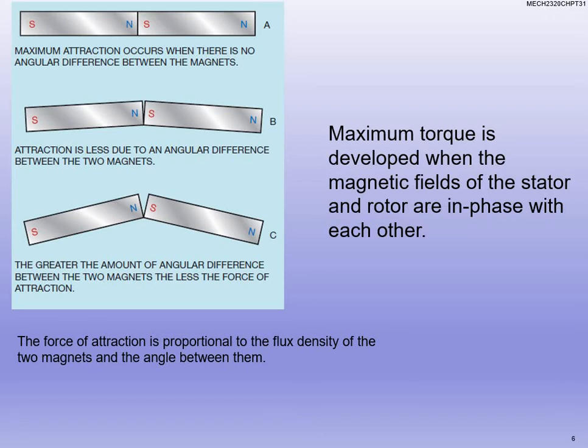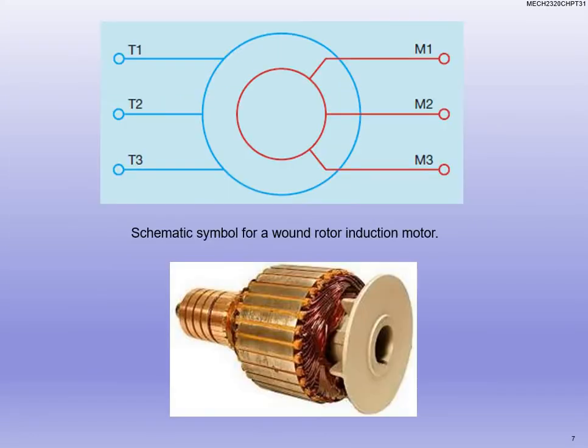But if we make a small angle that's off, one is going to lead the other. One will be stronger than the other. But when we're able to perfectly align them, we'll be at our maximum force. And that's really what we're doing with a rotor and a stator. We're creating the magnetic fields there, not physical magnets, but the same exact concept. That's how we get maximum torque.